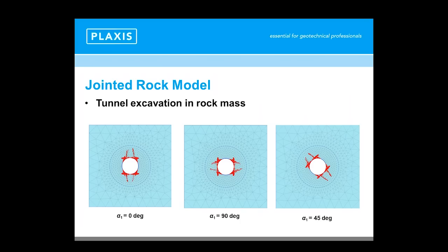Still, I would like you to bear in mind that it's still a model which is developed in the framework of a smeared approach. So there is no consideration of possible distances between rock joints along which failure could occur. It's still a smeared approach. So we are making the same consideration of the model regarding failure at each integration point.